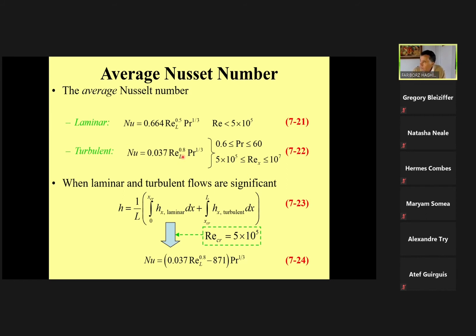Yes, sir. So basically, you can just use the last equation for any case? That's correct, this is more accurate, no matter the Prandtl number, no matter the Reynolds number. It has nothing to do with the Prandtl number. The Prandtl number is only a characteristic of the fluid. Here the Prandtl number is included anyway, both of them are to the power 1/3.